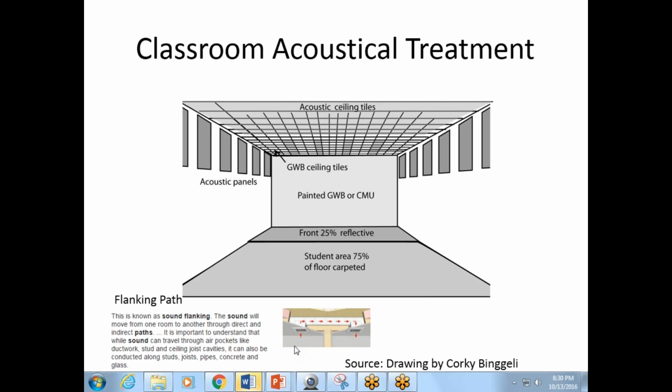If you were to stand there, you might be able to hear sound from one space to another space. Think about those ceiling cavities and applying some type of insulation above so that we don't have the problem I talked about earlier. So many things to consider, and even if we changed up the flooring materials between the two spaces, we might help by carpeting one space over another so there's not two hard surfaces going on at the same time.